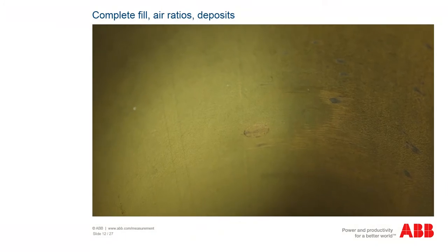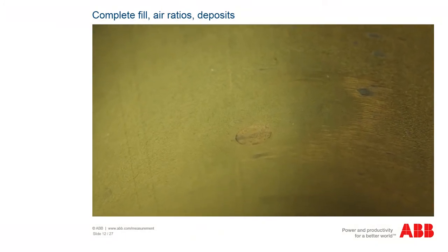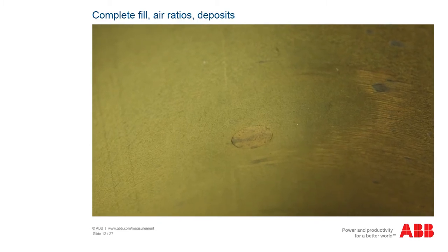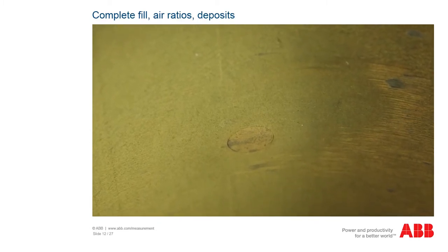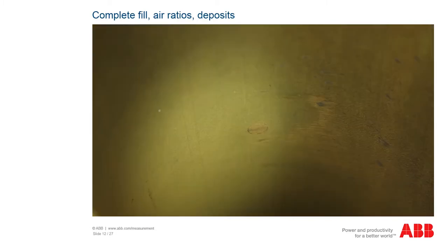However, it is not only empty pipes or gas formation in the pipe that lead to incorrect measuring results. The electrodes are in continuous contact with the medium to be measured. This can lead to the formation of deposits on the electrodes. Deposits in the device and on and between the sensors and electrodes can lead to malfunctions and incorrect measurements. A conductive deposit that establishes an electrical connection between the medium and the electrode leads to an incorrect measurement. A lower flow is indicated.